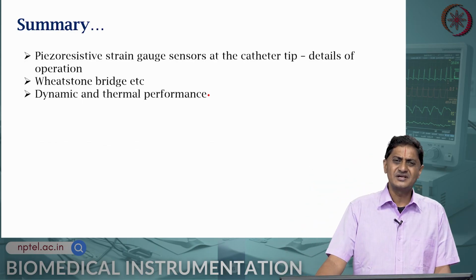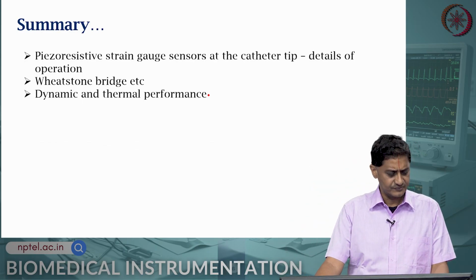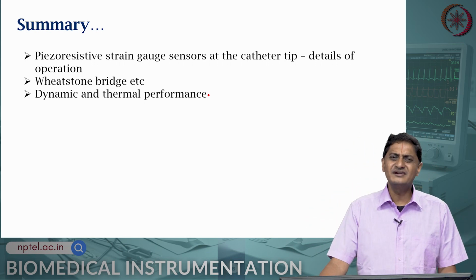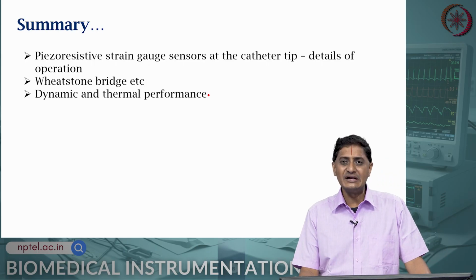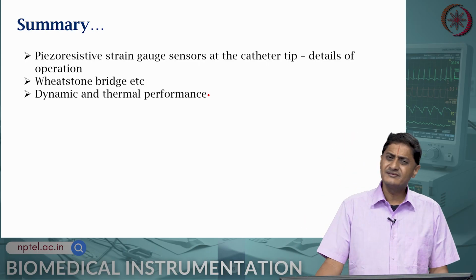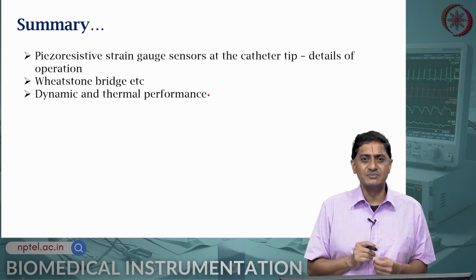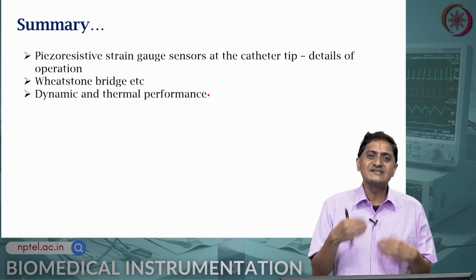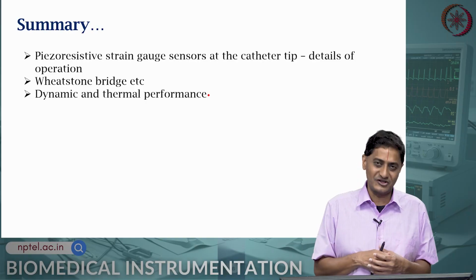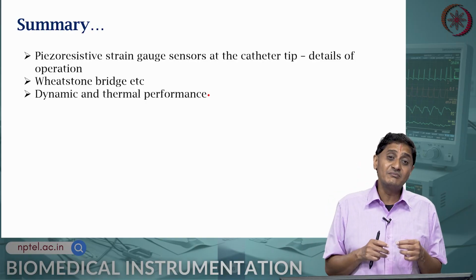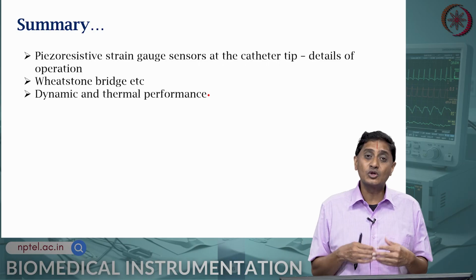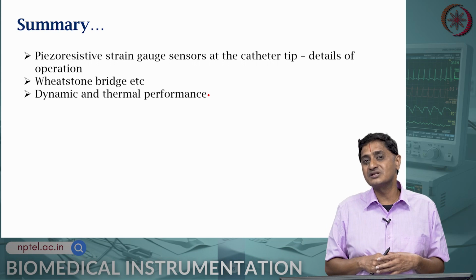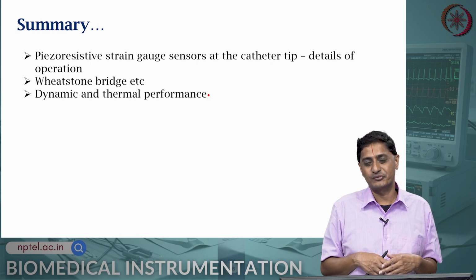But what are some of the constraints that you are working with? Essentially, your design must find a trade-off between durability and sensitivity. Why is that? If the material is too flexible, then too many cycles of measurements are likely to wear off the material. But if the material is too stiff, then a small change in the pressure is unlikely to cause a deflection in the diaphragm.